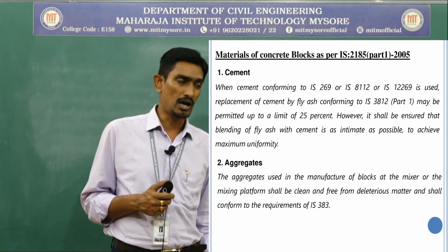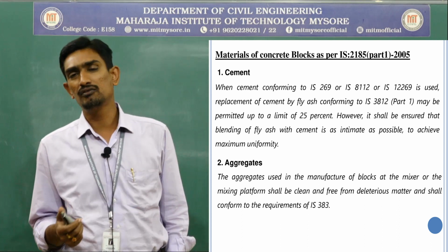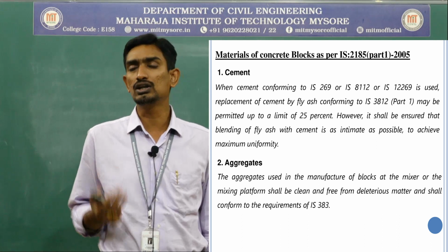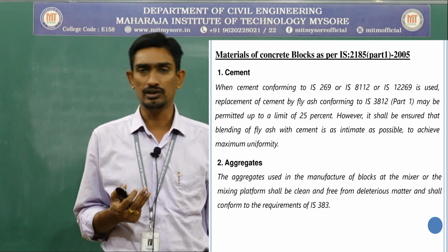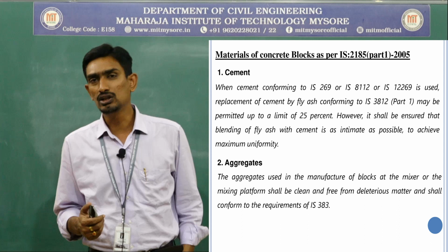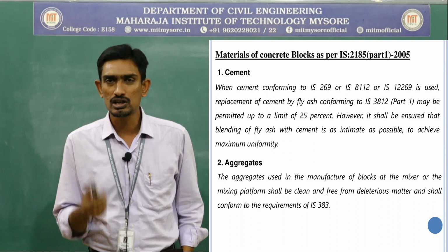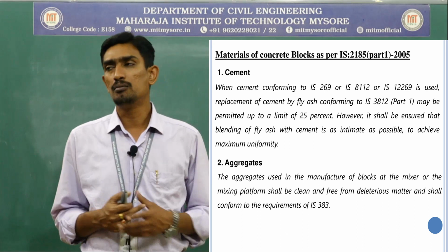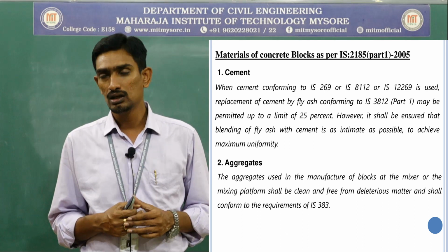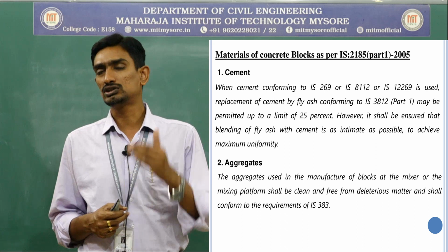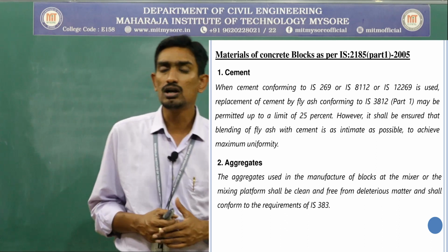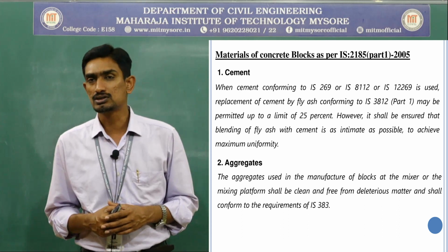So in order to manufacture the concrete block, we can use OPC or we can use PPC. If you want to go with a green concrete block, go with PPC. That's it. Likewise, the Jindal industry, a most famous industry available in Ballari which produces steel, also produces a waste called granulated blast furnace slag.